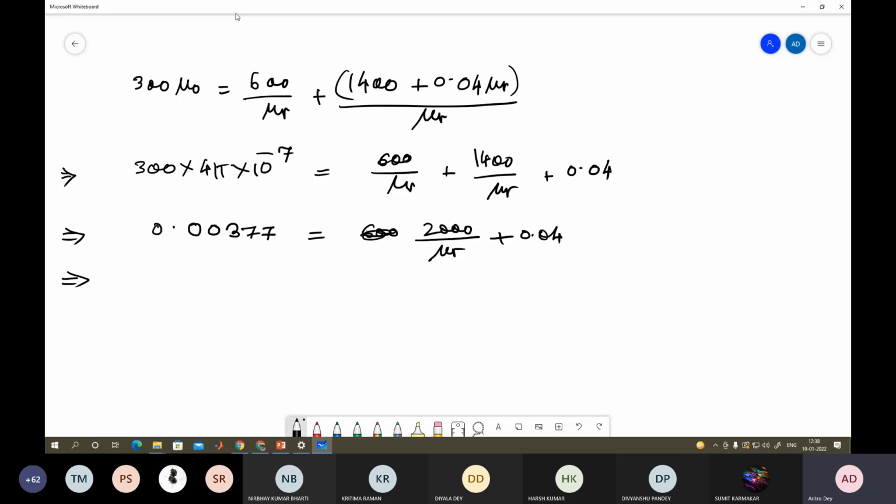So this is how you can expect the problem. Mostly it will ask what your magnetizing current is, so that you can develop a flux in the air gap, and that air gap flux will be given, or you will be given the other way around. The magnetizing current will be given and you have to find the air gap flux. That is also possible. Whenever you get circuits like this, you will always have an electrical analogy for that particular magnetic circuit, and you can solve it that way.